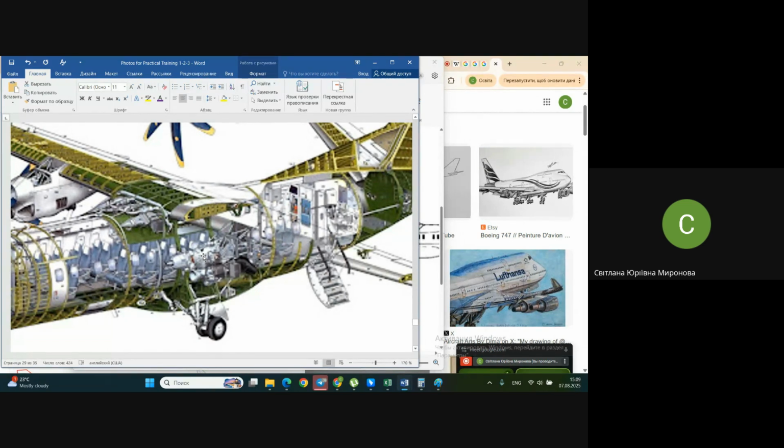For military airplanes, mid-wing is rather a typical decision. Moreover, I have seen structural decisions for light airplanes, so-called business jets, when they have mid-wing, really. It seems like mid-wing, but in this case they have no center wing. And in this case, they have reinforced frames here, much more reinforced than in our picture right now.